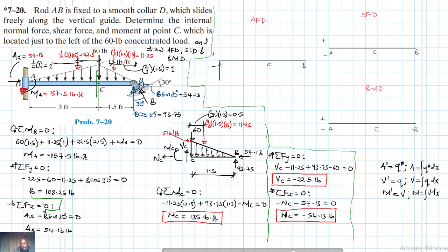Let's say this is our value there, and between A and B, we don't have any axial distributed force, and we don't have any intermediate concentrated axial forces. So because of that, our slope is just going to be 0 up to B. Then later on at B there, they'll add, and then algebraically we'll have a summation of 0. So this is negative, it's in compression. Alright, is that okay? Let me bring this a little bit closer like so.